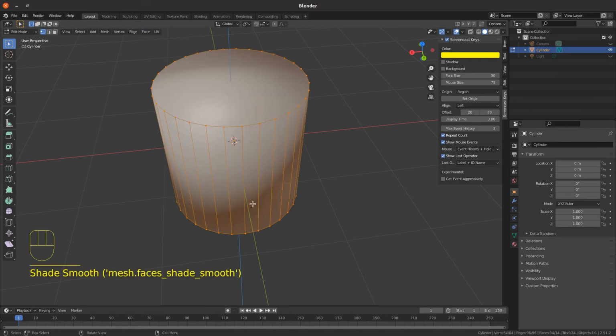This causes shading errors because we've got a 90-degree corner that we don't want to smooth over, because it becomes too difficult for it to calculate how you would actually shade that as a corner. Where these are shallow edges, it's easy to work out how to adapt the face normals to make it look like a curved surface rather than a faceted surface.